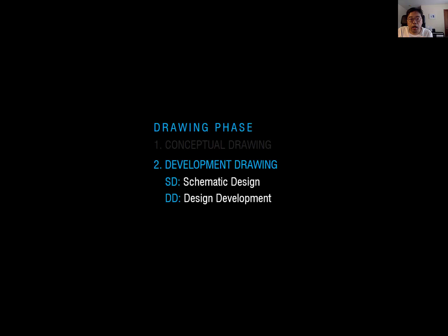Design development has to include much more detailed information for the plan, section, and elevation. It also has to include the wall section, how floor and wall are assembled together, and also more detailed finish types. It means more code analysis and lots of detailed information here. So during the DD phase, we usually get the first cost estimation, to know the actual cost estimation of your project.